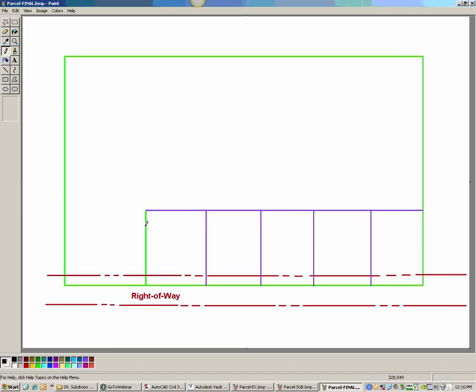If you need to show existing parcels on the existing conditions plan, those need to be in the existing conditions file. If you are generating a subdivision plan that breaks all the areas down to divide up the land, that set of parcels that breaks everything down should be in your design file. So if you're in transportation, be your T job number file, land development, L job number. And then if you need a final set that shows, after the subdivision has been recorded, maybe you're going to come back in with land development and you need a set of parcels that reflects that the recording and the subdivision has already taken place, you would need a third drawing that has the final set in there.